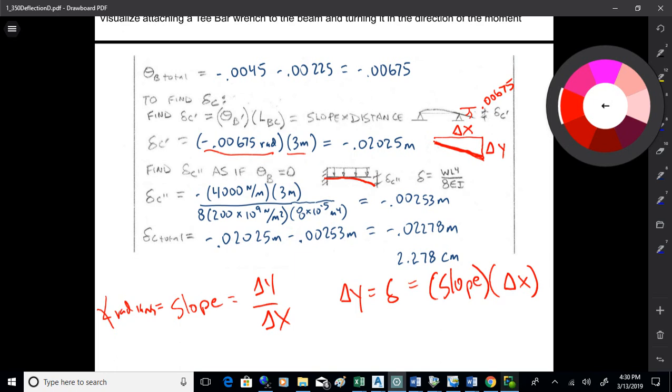The best way I can model that is to treat it like a cantilever. Okay? So I've got this beam that's running over that point at B, a continuous beam. That acts kind of like a cantilever support at B. And that beam, as it extends beyond B, will bow down on account of that load. That will be minus wL^4 over 8EI, and I'm getting that from the cantilever table with a distributed load on it, the third case down on the cantilevers.